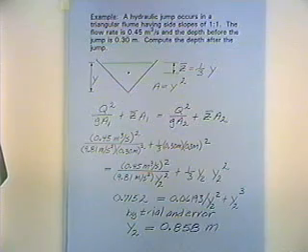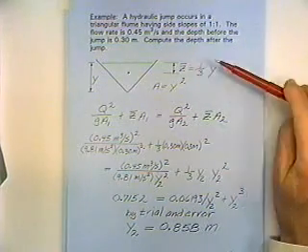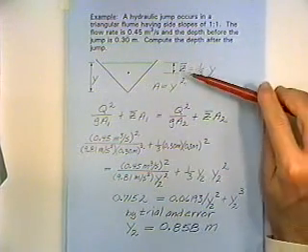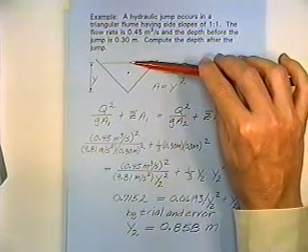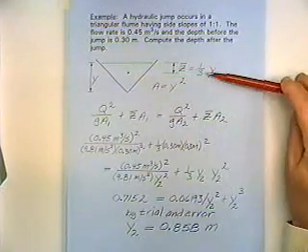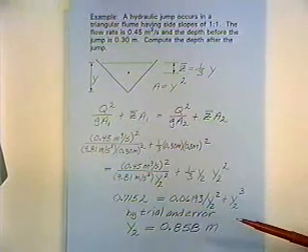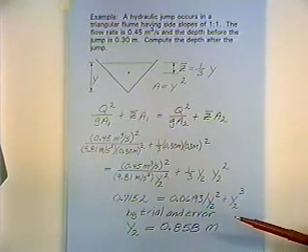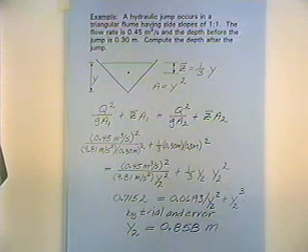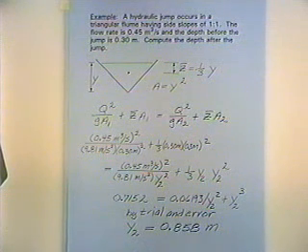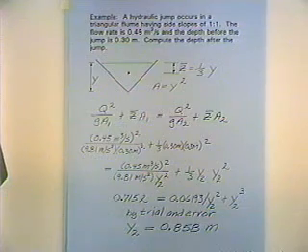The area of this triangle is y squared. The z bar, the distance from the water surface to the centroid of the area, is 1/3 y. From that geometry, we can plug in for z bar and the area, and we know everything except the depth. Then we can solve for the depth. Given the depth before the jump of 0.3 meters, the depth after the jump is 0.858 meters.